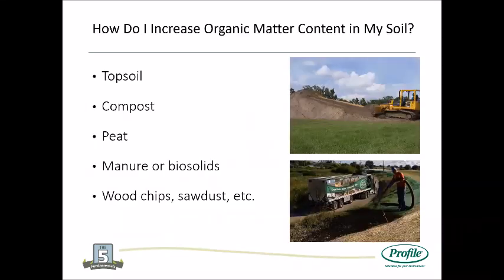So again, now we need to increase that organic matter content in your soil. Stockpiled topsoil is a very common BMP, but once you stockpile it, how biologically active is that topsoil towards the bottom of that stockpile? It typically becomes anaerobic relatively quickly, and a lot of the beneficial constituents really die off quickly on those stockpiles of topsoil.